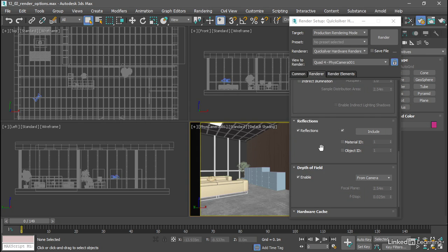Again, this is not ray tracing. It's automatic reflection mapping. The object becomes a camera and takes 6 pictures of its surroundings and then maps those pictures onto the object as reflection maps. Automatic reflection maps have a lot of problems, especially in areas where the objects are too close to one another, and that will cause the reflections to fail.